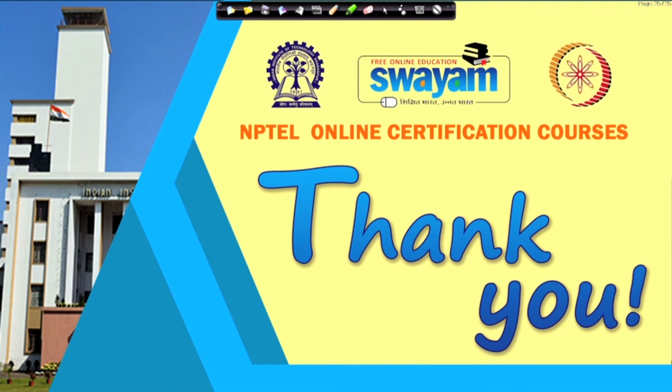So, this is the basic introduction of the program evaluation and review technique. In program evaluation and review technique, we use the probabilistic approach to solve the network, and that is why, compared to the earlier critical path method where a deterministic approach is taken, the program evaluation and review technique, being a probabilistic approach, gives us a little bit better result. At least you can have a reliability, or the probability of achieving the target can be assessed using the program evaluation and review technique.